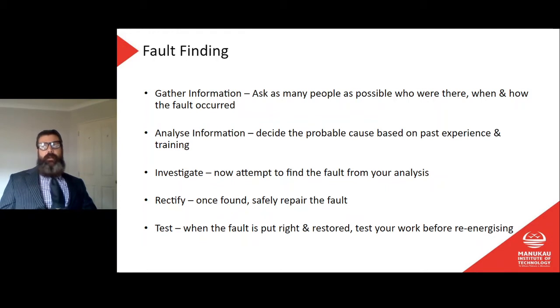thermal effects overnight, and I ignored it. I went to the site two or three times and just went, no, it's fine, everything's fine, until I actually went, well, I keep coming back with the same fault. Let me check a bit further, and then found, yes, there was a leak. I don't know how much fuel leaked into the ground in the time it took me from first going to that site to actually finding that fault and fixing it. But I tell you what, that's on my head. I did that. I didn't do my fault finding properly, and now we've had fuel go into the ground, a release of hydrocarbons into the environment due to my laziness or poor fault finding or what have you.